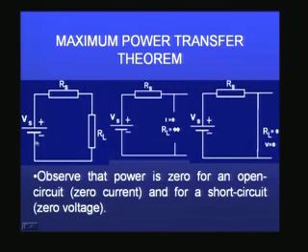If I take a small example, I have a battery here which is connected to two resistors, Rs and RL. What is this Rs? This Rs and Vs, as you can see, is nothing but an actual voltage source. Any voltage source can be represented by an ideal voltage source Vs, which has no internal resistance, and Rs as the series internal resistance across that. So together they form any actual voltage source. RL is the resistance I want to connect this voltage source to.